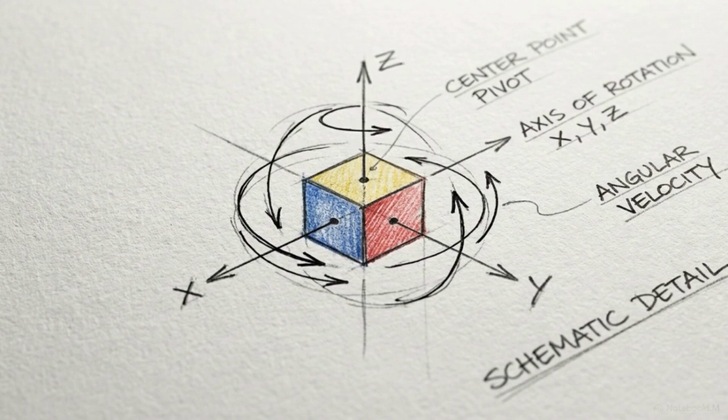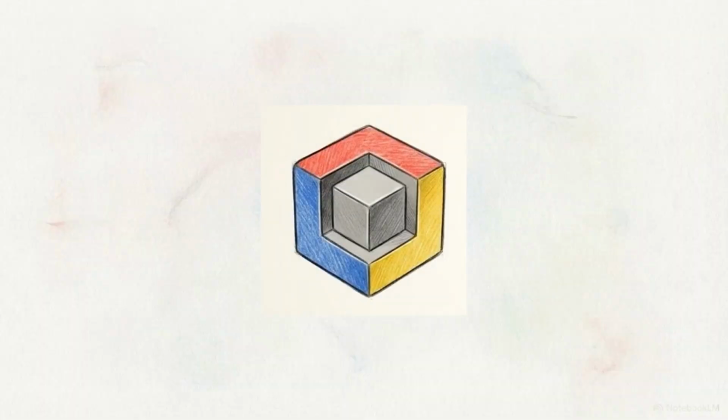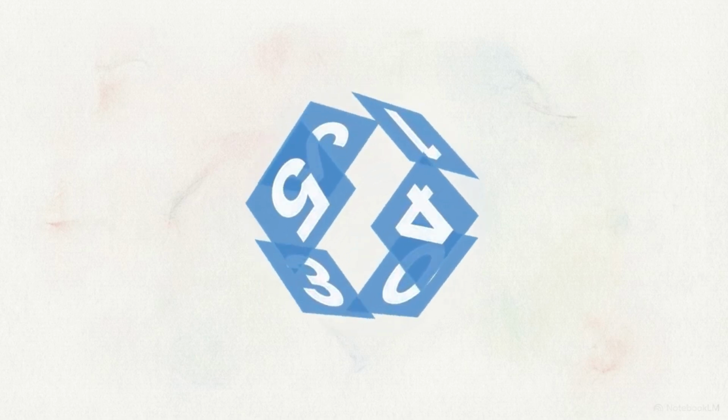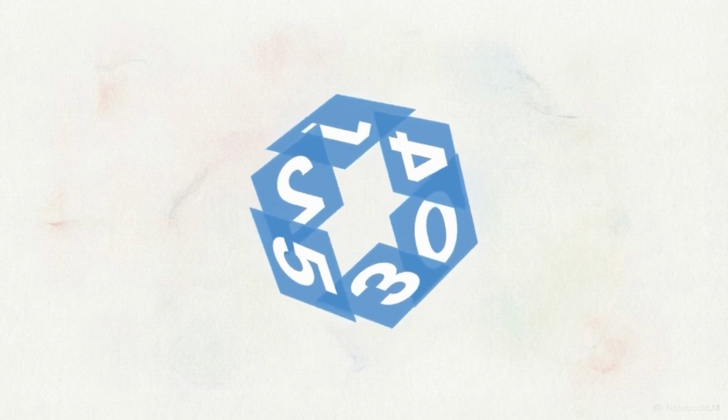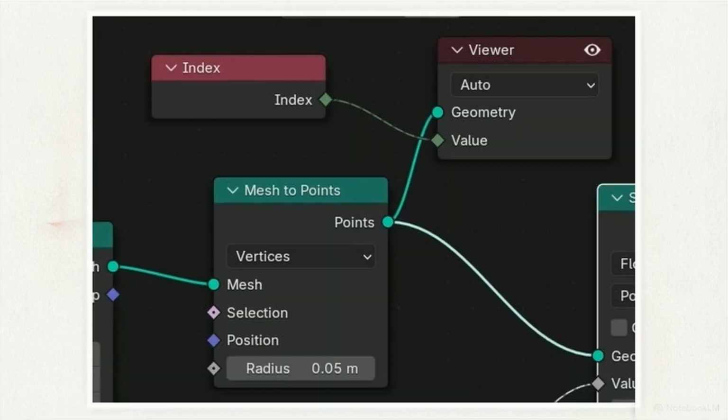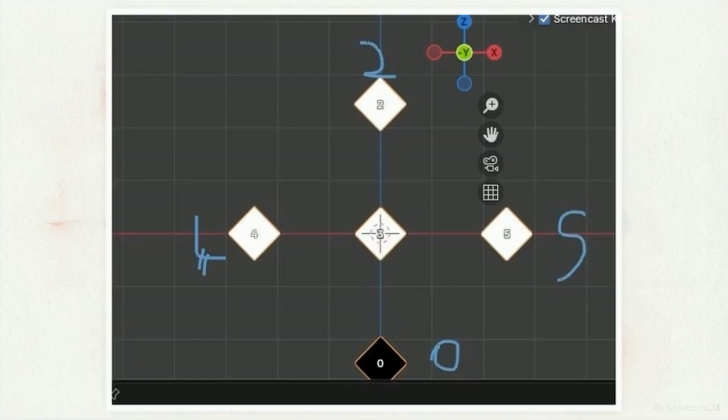To paint the cube, we have to identify the 6 faces of every cubelet. Blender assigns each face a hidden ID number called an index ranging from 0 to 5. Open the Viewport Overlays menu and enable attribute text to see these IDs on the model. We can visualize this data by connecting an index node through a mesh to points node and plugging it into a viewer. In the front view, you can see the numbers mapping to the points.